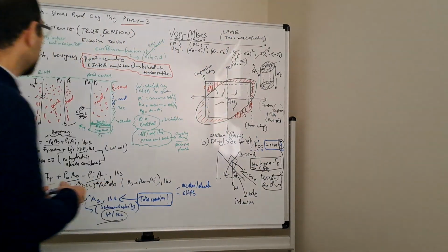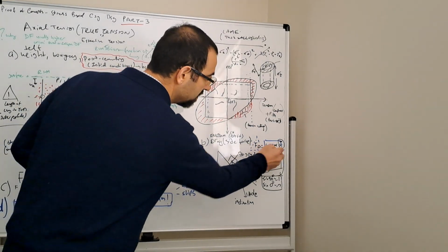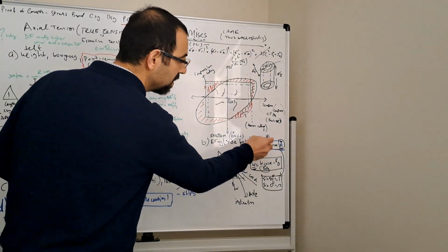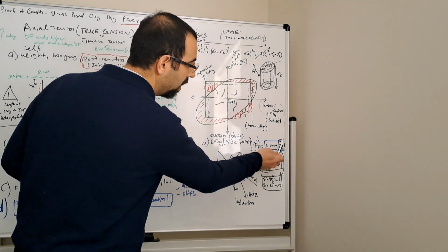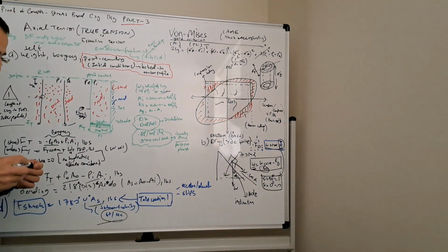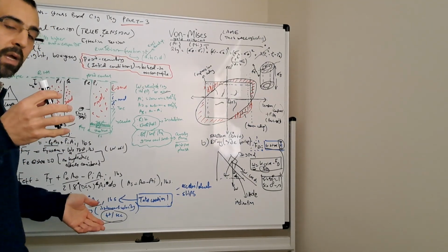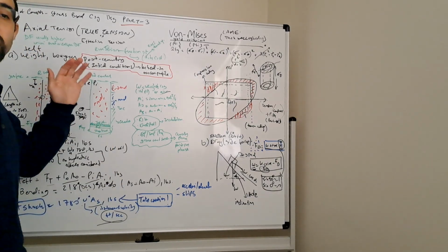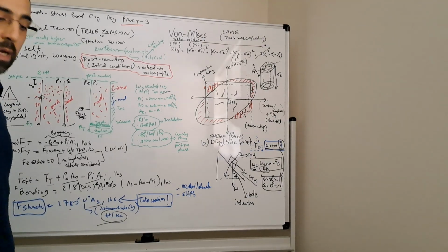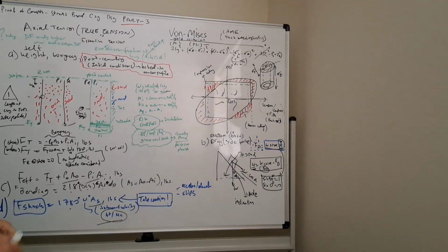So when we are running in hole, we take into account friction. What we need to take into account is this value over here: weight will be reduced by approximately weight times sine alpha times the friction factor. As I said, it's a combination of open hole and case. Some companies use different factors, or some companies might say let's use one friction factor for the full open hole and case. So it really depends on different approaches.